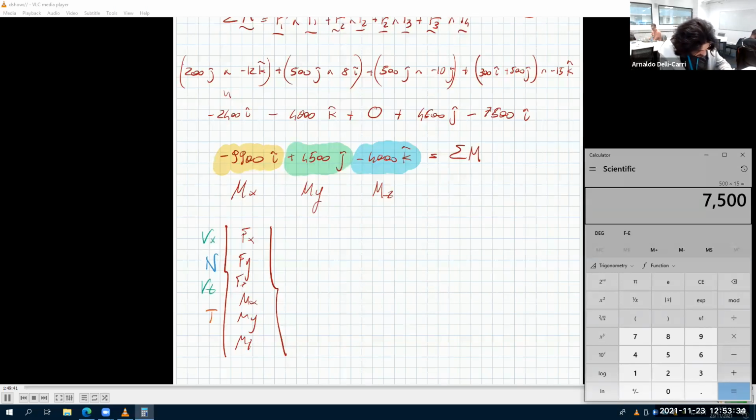And we have Mx and Mz as bending moments. Okay, so these two are bending moments. These two are shear forces. Now we have normal force and twisting load, so you can find here the stresses.